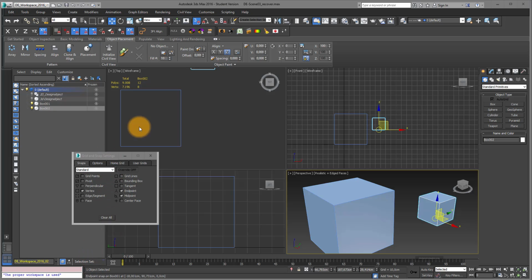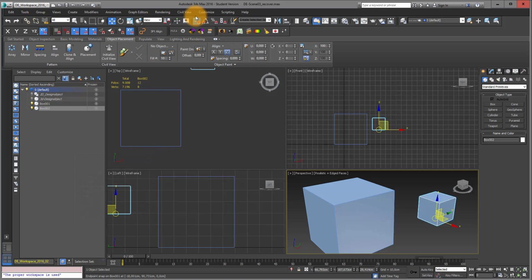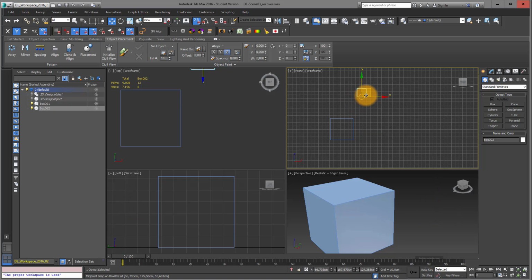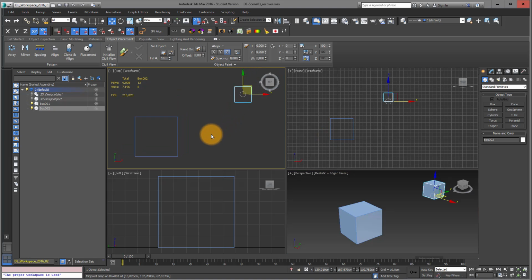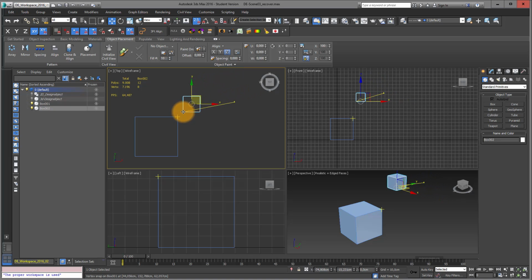I normally don't use this 3D snap function. I normally always use the 2.5D, and I'll just show you what's happening if I just move this object out again a little bit, and I just have my snap toggle on, and then I can again choose this corner, move the corner, and you see what is happening. It still snaps, but it doesn't have any impact in terms of the Z dimension. And this is really handy.